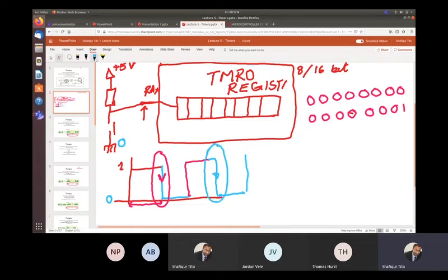These events are the falling edge of my switch, the falling edge of a signal. So the pressing of the switch is related to the falling edge, and this pressing of the switch can be counted by this register as an event. So I can store in this register depending on this falling edge. This is how this register value can be changed.